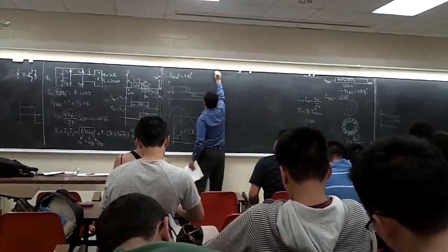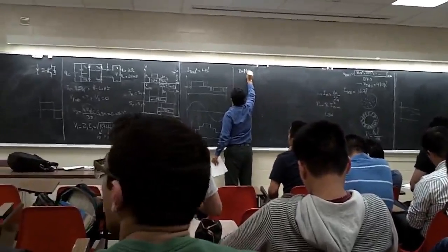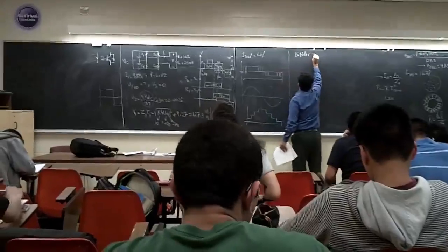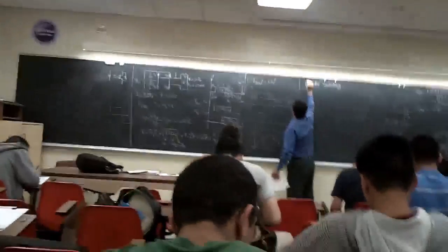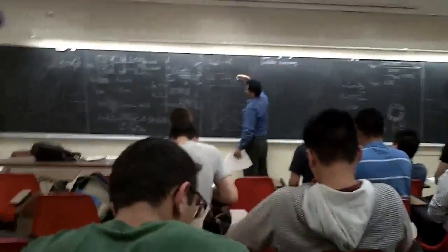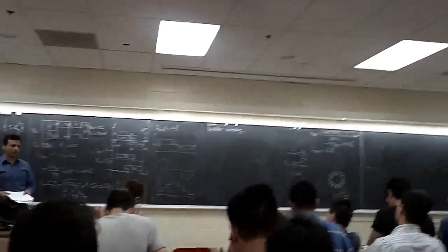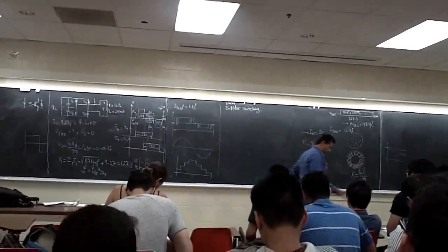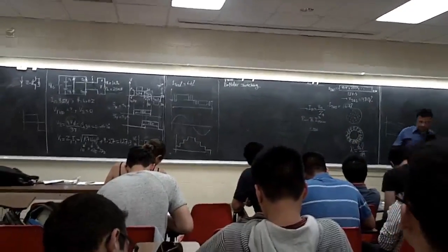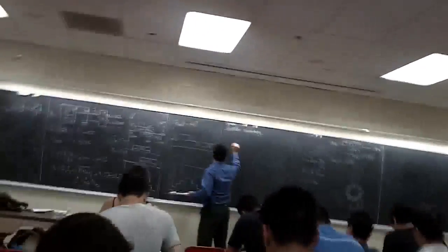Now we're going to do bipolar switch. This is the PWM. By the way, we came to the PWM. As soon as you see this one, start to chop those signals. We call it pulse width modulation. But again, we have the single phase inverter. Let's go back to the same thing we had before. Half bridge.